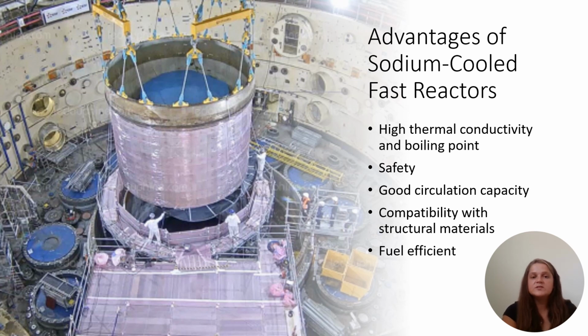The components of a sodium-cooled fast reactor have excellent compatibility with structural materials under the deoxidization condition. Corrosion and surface changes of structural materials can be controlled during the plant's lifetime by controlling and moderating concentrations of impurities. These can be hydrogen, oxygen, etc.